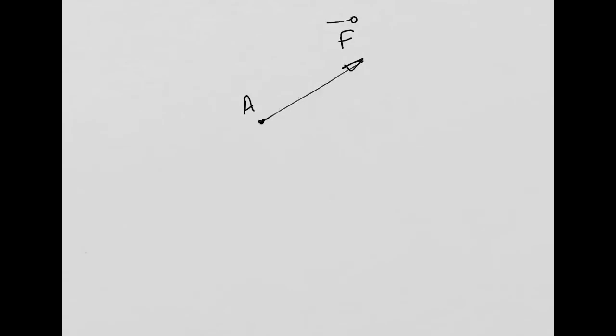All right? And imagine that you have now a force which I'm going to say is equal to minus F applied at a different point B. So these two forces, F and minus F, they have the same intensity, same norm, or the length of these vectors are the same, but they are opposite, right? So if I calculate the resultant of these forces, which is the summation of all the forces, this resultant is going to be equal to 0, because they are symmetrical forces, they have the same norm, so they cancel each other, right? So we call this system of these two forces in these conditions a couple.